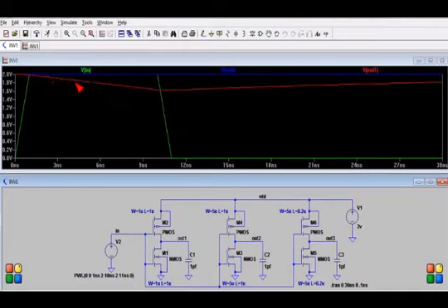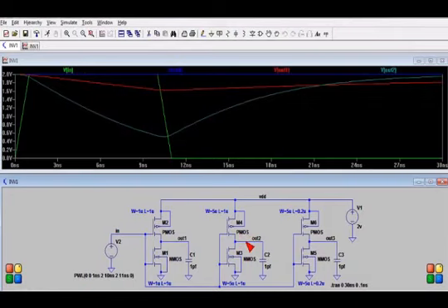We see that the output starts to discharge the capacitor, but never really does a very good job. It never gets to a logic 0. So it's just really much too slow. Let's look at the output of our second inverter. And we see that the wider transistor, by increasing the width by a factor of 5, discharges faster, but never really gets to a logic 0.